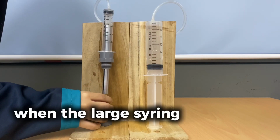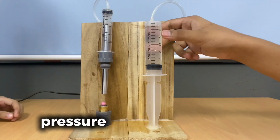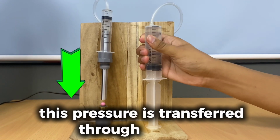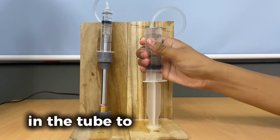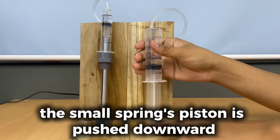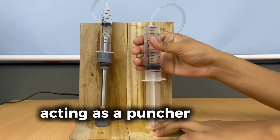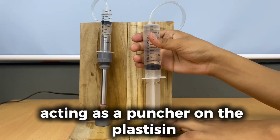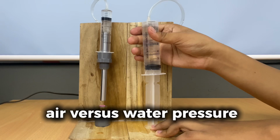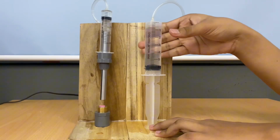When the large syringe plunger is pressed, pressure builds up inside it. This pressure is transferred through the fluid in the tube to the small syringe. The small syringe's piston is pushed downward, acting as a puncher on the plasticine. Depending on the fluid types, air versus water, pressure transmission will vary.